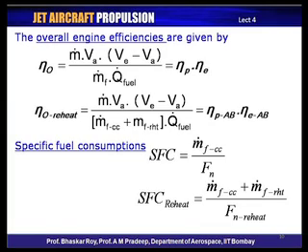If we simply reconfigure that efficiency for reheat purposes, we shall see here that we have two kinds of mass flows over here, whole thing multiplied by the fuel that is pumped in, and the fuel is pumped in also twice, once in the combustion chamber, once in the reheat zone. And then of course, you have two efficiencies here, one the propulsive efficiency of the afterburning engine, and then the energy conversion of this afterburning engine.